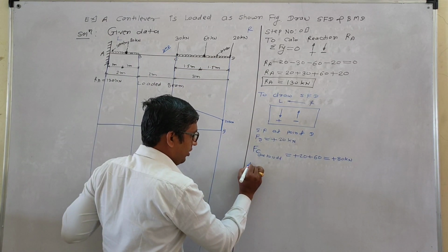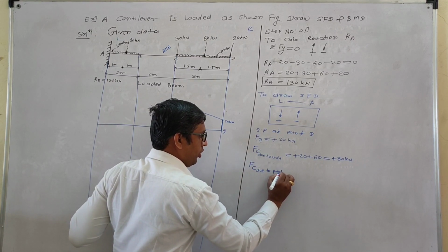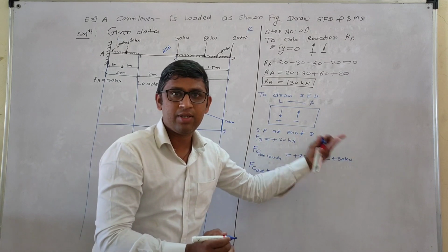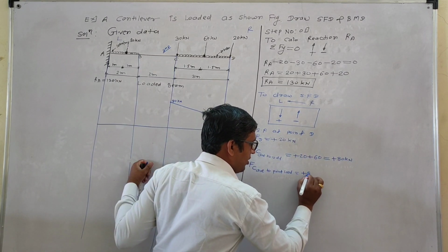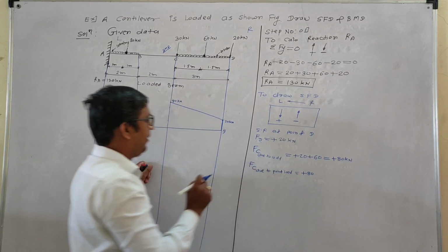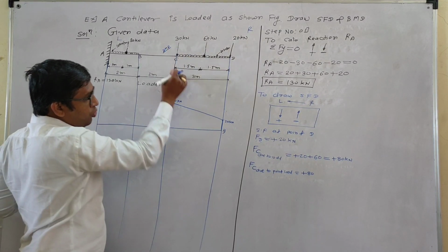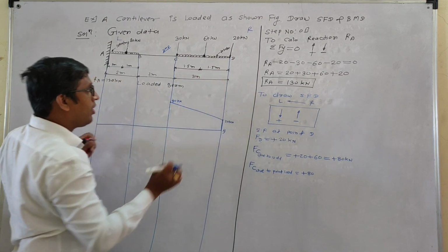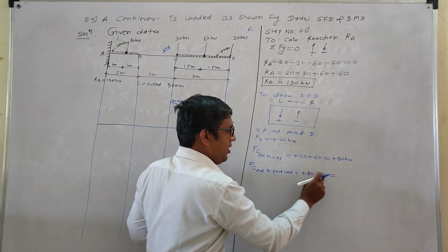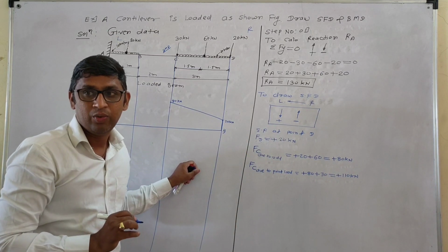Okay. The next, again, shear force at point C due to the point load. Shear force means what? Algebraic sum of previous plus 80 kilonewton. Don't forget to take the algebraic sum of plus 80. Then another point load is at point C, 30. You have to take 30 goes downward. Downward means plus 30. Plus 30 is equal to 80 plus 30, plus 110 kilonewton.